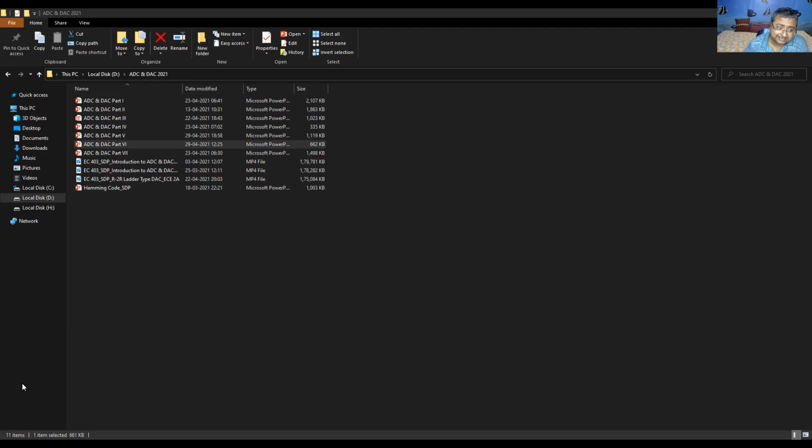For T greater than T1 to T2, the output of the integrator is negative, and its value is increasing. Due to this, the output of the comparator will be logic 1. Then the up counter will count in the up direction. This process will continue until the output of the integrator becomes 0 after N number of clock cycles. Okay. How many clock cycles are there? That depends upon.